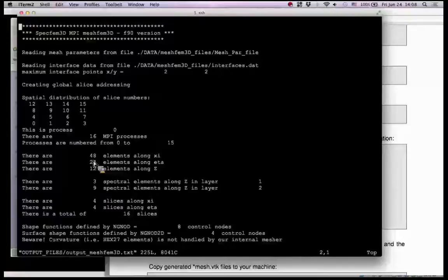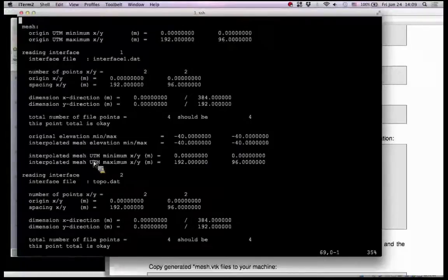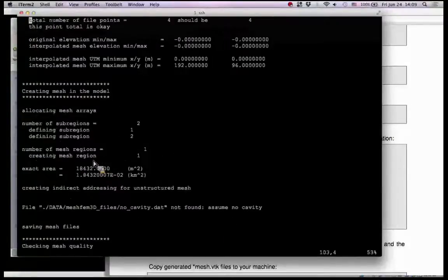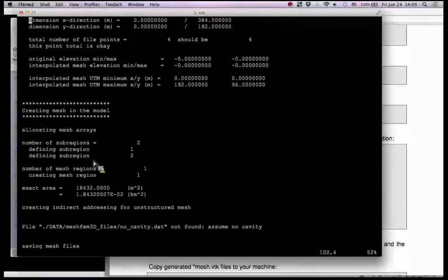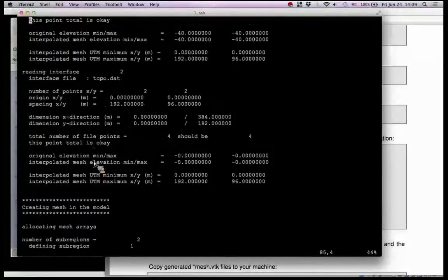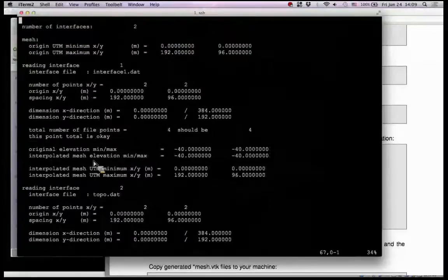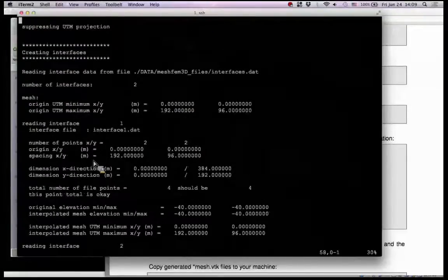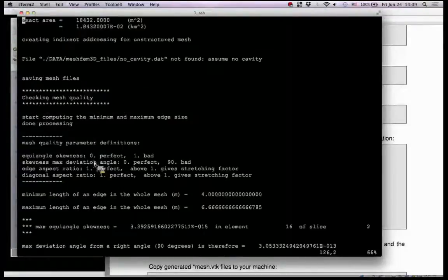So the information from the output of mesh, just gathering all information, so we go quickly. What is important here at this stage is the quality of the mesh can be assessed through the ratio of the elements, dimension, size in X and Y direction.